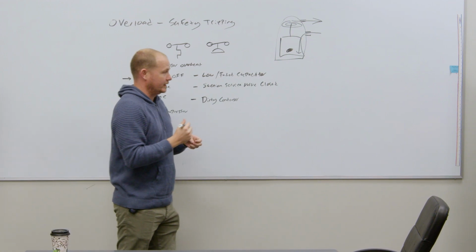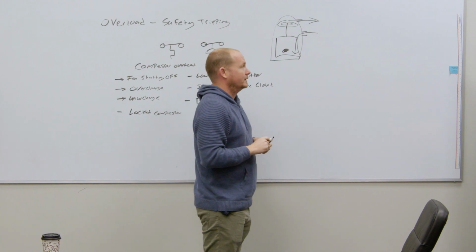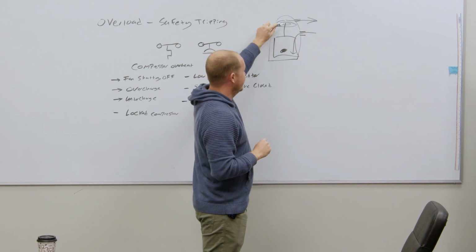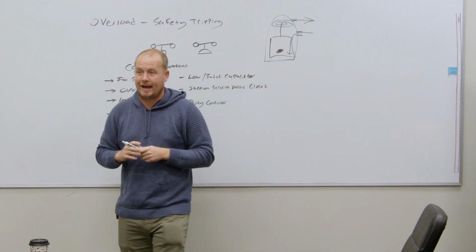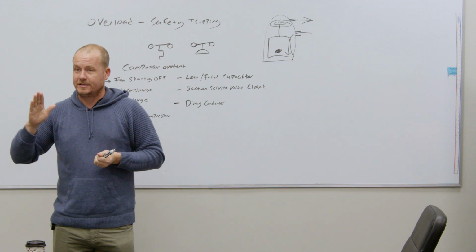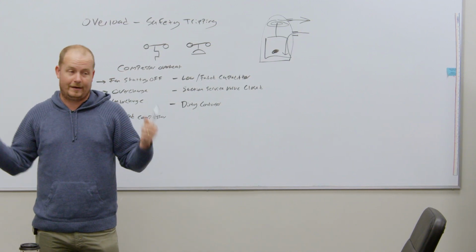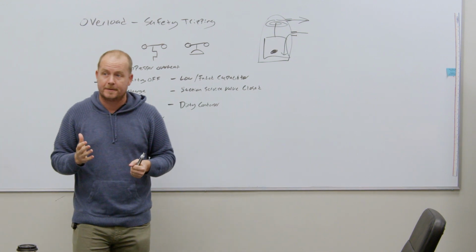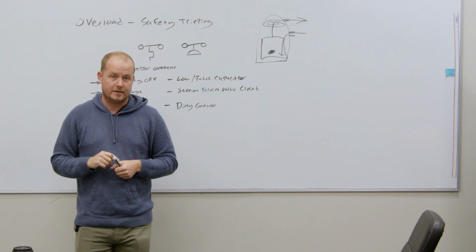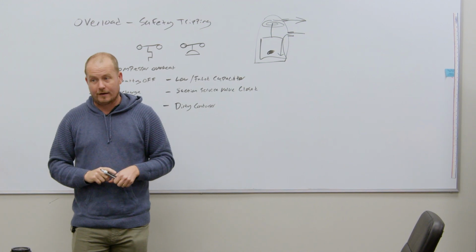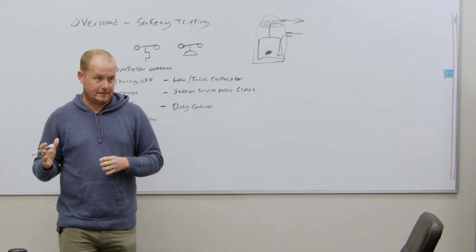Now, there are actually some compressor manufacturers nowadays that certain types of mechanical problems, like when they unload or little ports or whatever, will actually overload and redirect some of that hot gas right to the thermal overload. Like when it has certain conditions, it actually tries to blow that discharge gas right on the thermal overload so it trips quicker. So you don't have to heat up the whole compressor, which is why you'll notice some compressors cool down quicker than others. You have some older models of compressors that you work on that just seem like they always take forever. And it has to do with the thermal mass of the compressor as well as some of those internal designs.